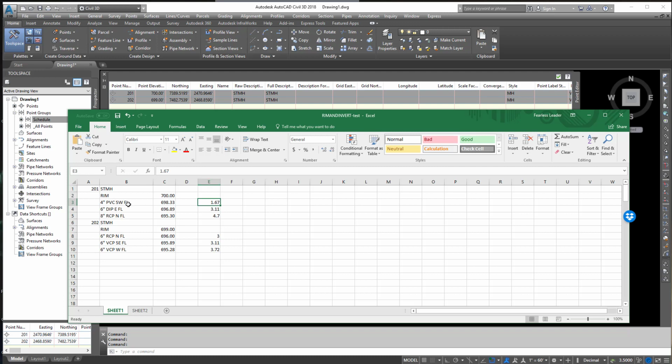So for mine, I have a 12-inch RCP. And again, you can use caps heading north with a flow line. And the invert or flow line of that guy is... And again, I'm going to let it do the math for me. All this is set up. So this is my dip here. So I'm going to type in -6 and hit enter, and it'll automatically calculate it. Oops, sorry. It's just supposed to say 6. There we go. Otherwise, I'll get the opposite reaction.